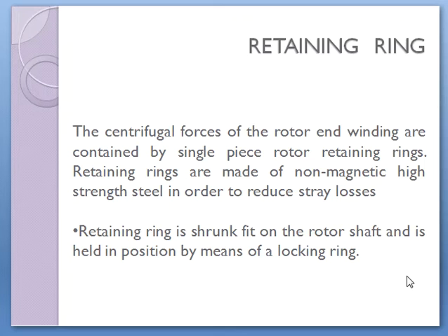These retaining rings are first heated so that they expand a little, and then they are inserted on the end of the rotor, shrunk fit on the rotor shaft and held in position by means of a locking ring.